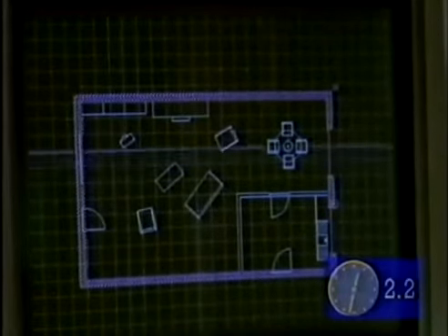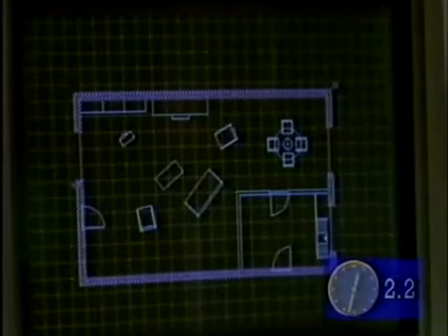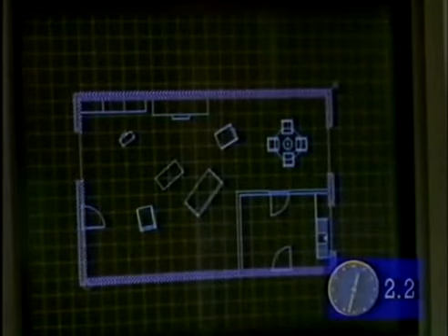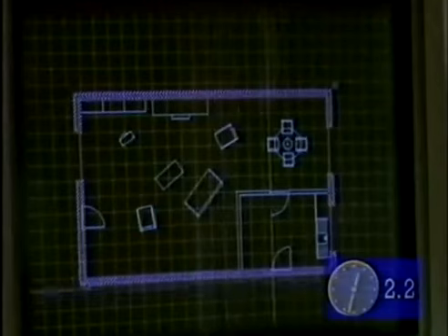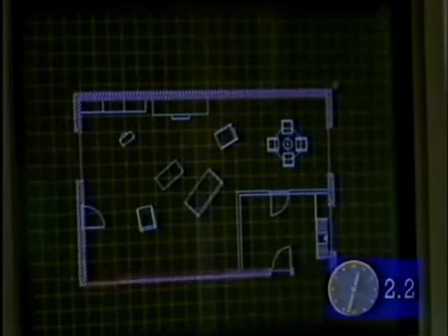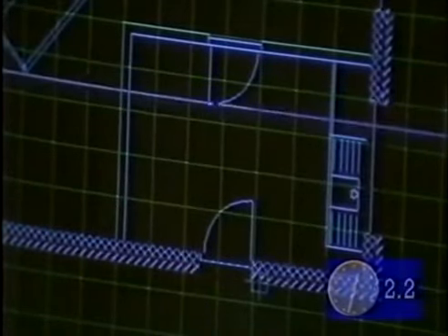So I've got a window over here. Again, J option, and place it in there. And really we need to do doors now. The doors as well. So again, select it from the menu. It's another symbol for the door opening. Select the wall, J option again, and again point to the jamb where I want it to go in. Now these door openings and the window openings could be variable as well. These have been previously defined.